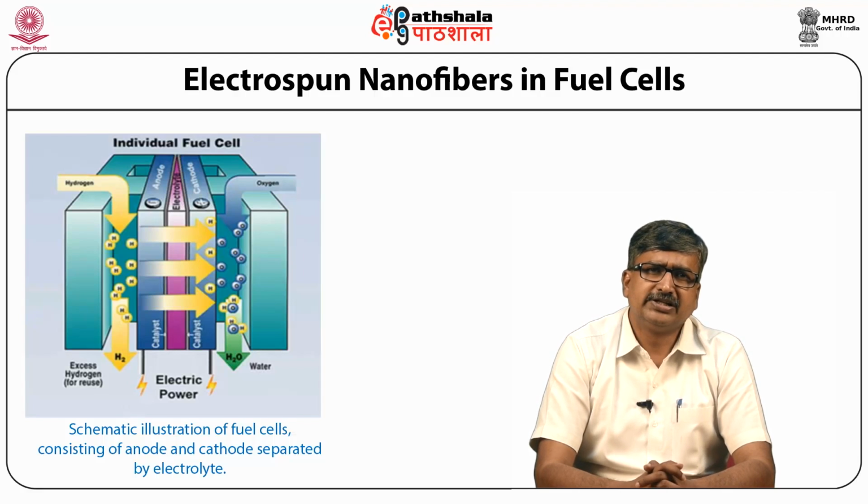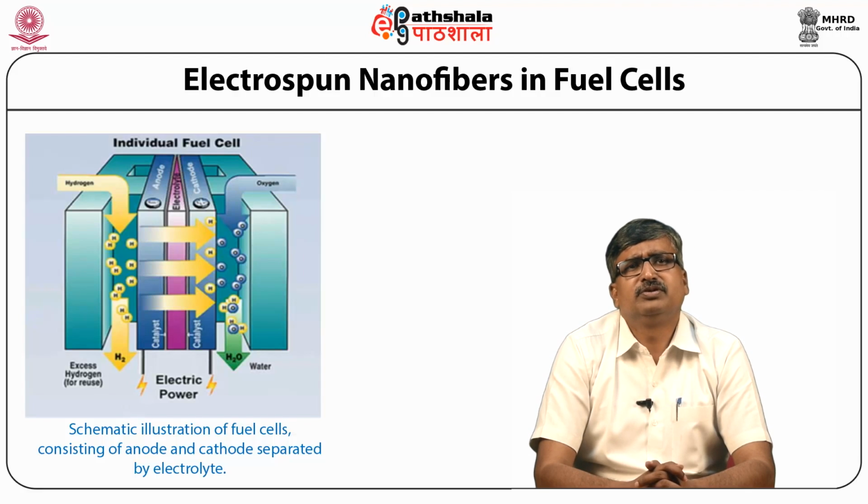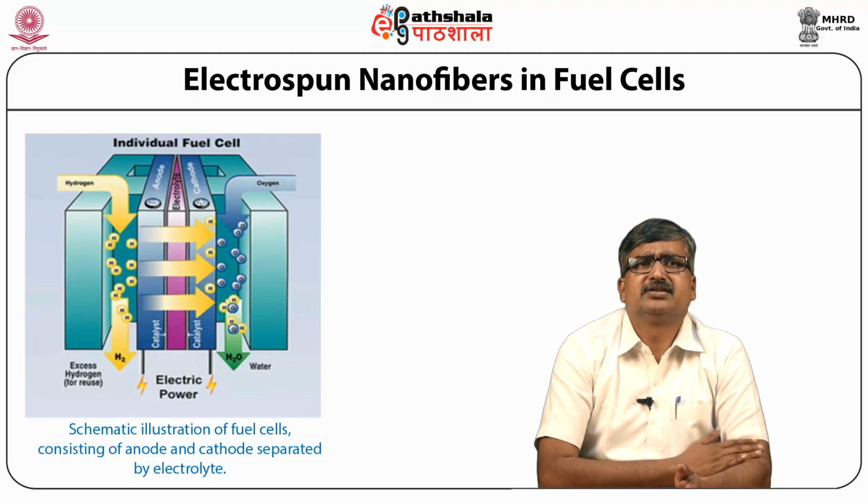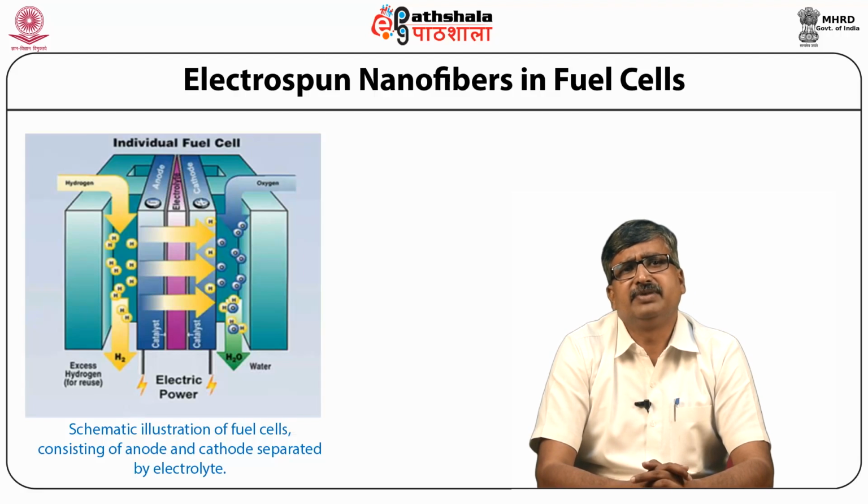Recently, electrospinning technique has been introduced into the fuel cell for fabrication of high efficient catalyst and proton exchange membrane. In principle, electrospun nanofiber based catalyst and proton exchange membrane offer a good opportunity for high efficient fuel cell, driven by their large surface to volume ratio and controlled diversity in compositions.